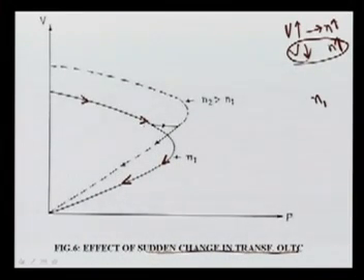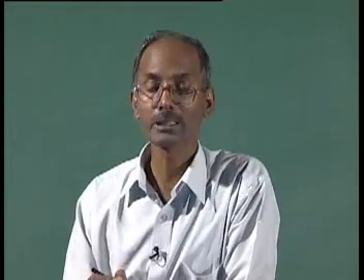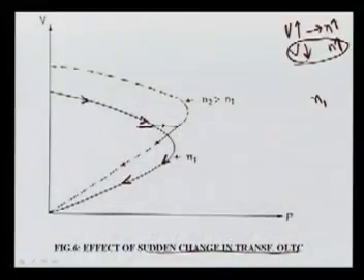If the reduction of the voltage goes beyond a certain value here, suddenly we increase the tapping, meaning we want to increase the voltage here. What happens here, the voltage will try to stay constant and it will come here, and you can see at this N2 tap our PV curve will be this way.